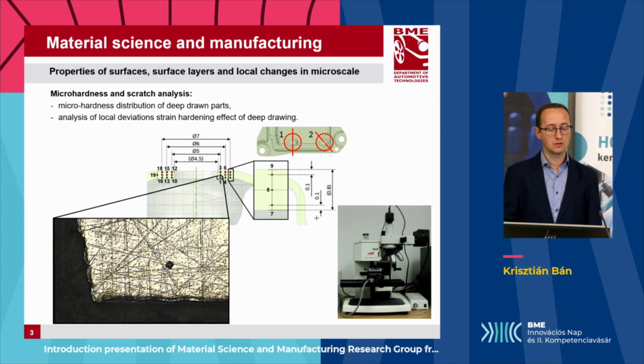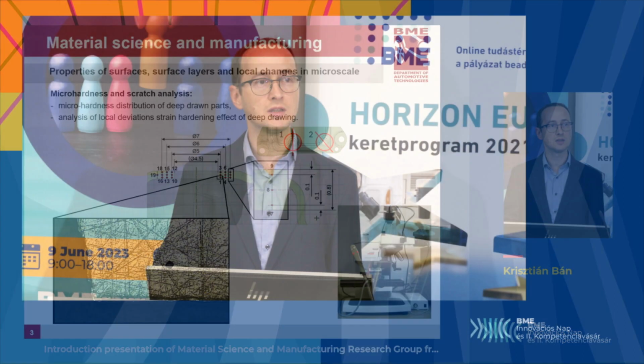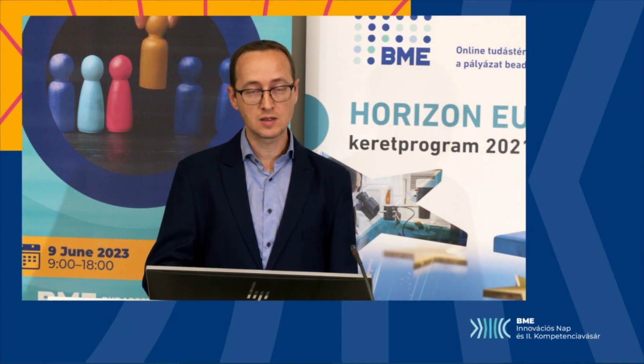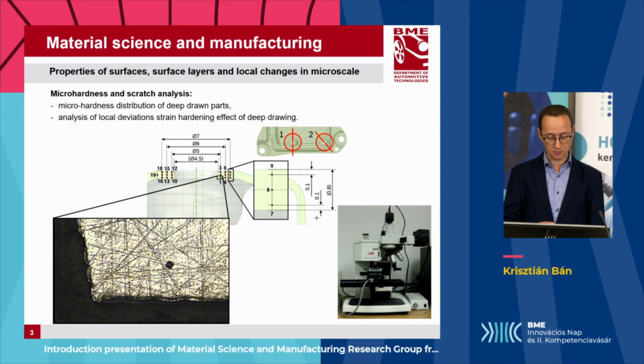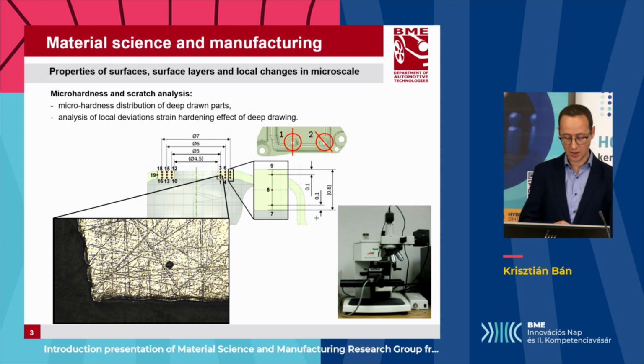In the same field, we had another examination which was dedicated to determine the local deviation of strain hardening effect in a deep drawn part. This mapping was carried out with micro-hardness measurements in predefined points of the deep drawn part.